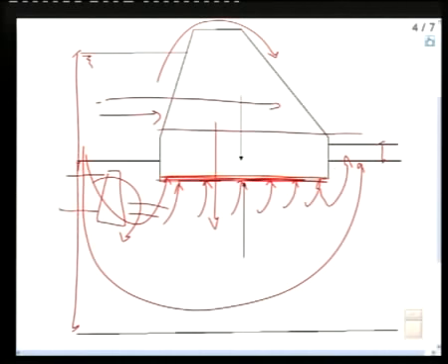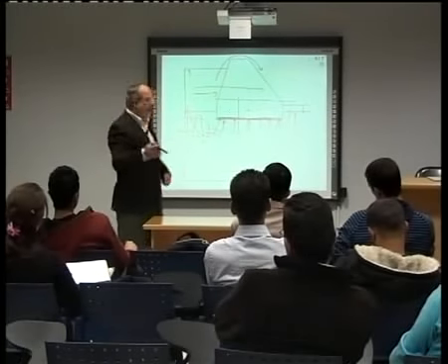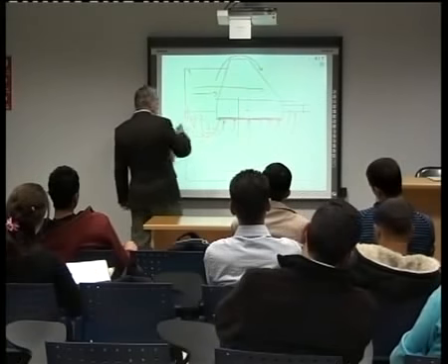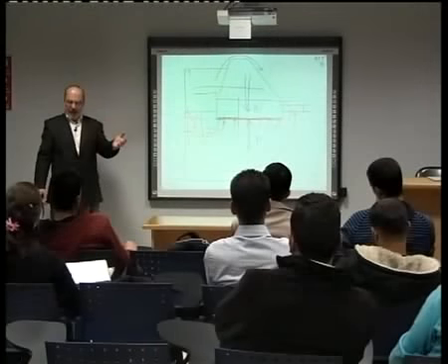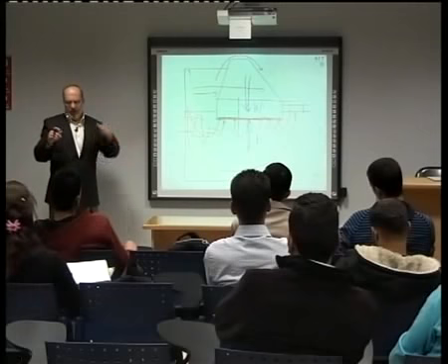What do I have to do to make sure the dam is stable or not stable? I have to compare between two loads, right? One load is the weight, compared with the pressure. I have to compare W with P. If W is more than P, then it's safe. Because I don't want to speak about settling.